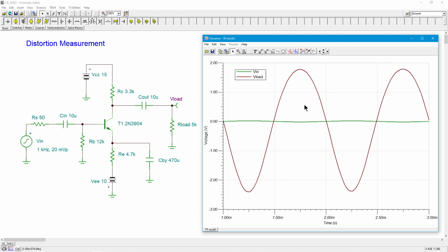Now, in the old days, when we would make distortion analyzers, at the output of the amplifier we would put in a very sharp notch filter that would get rid of the original sine wave that you started with. All you would be left with would be the harmonics. We would then put that harmonic-rich signal into a true RMS reading voltmeter, and whatever that comes up to, we would compare it against the original signal and derive a percentage from it.